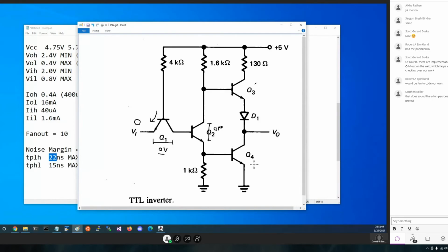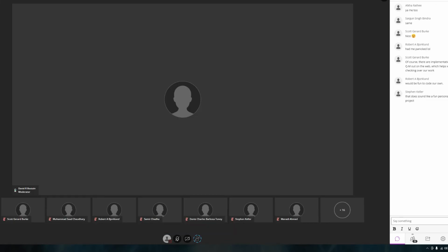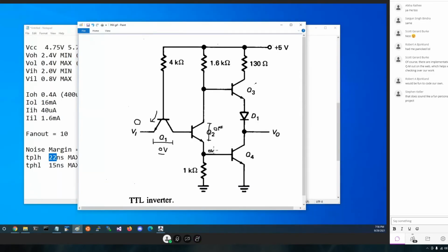Why? Right, we know here that this is not a 0.7 volt difference. As a matter of fact, it's slightly reverse biased if this resistor were doing anything, but at best it's 0. If we have 0 volts here and 0 volts here, there's no way we can get 0.7 there, is there? That's going to be 0 volts. Therefore, this transistor has to be off.